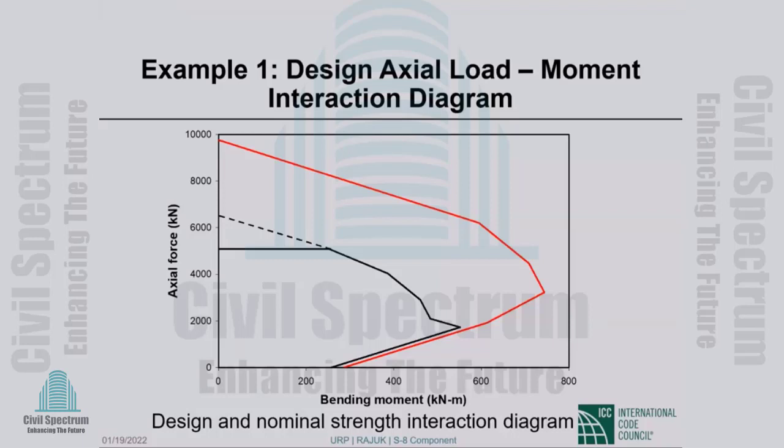Yeah, that's totally fine. What the 6 inches is: if there are two bars more than 6 inches apart, then the bar that is more than 6 inches apart needs to be laterally supported by a corner of a tie or a cross tie.